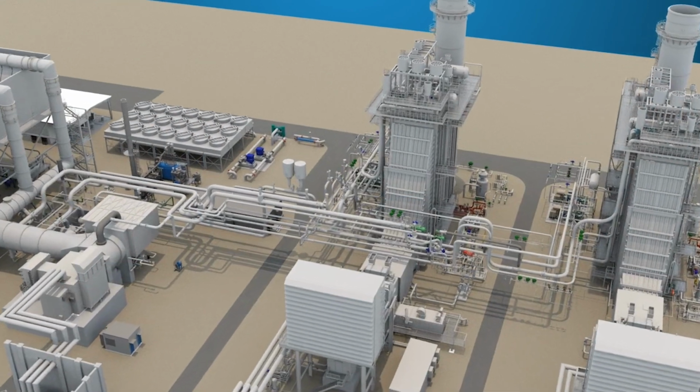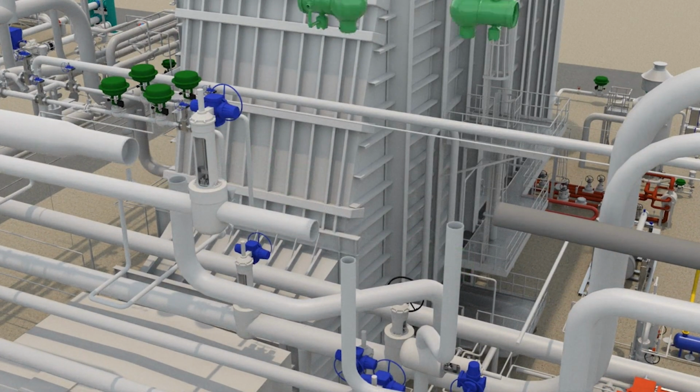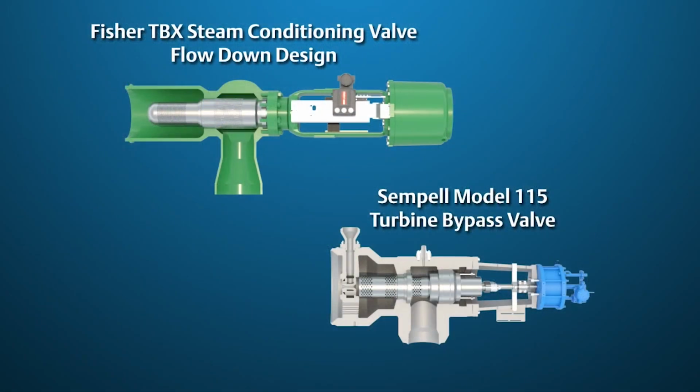In many cases, if there is sufficient headroom for the actuator, CVX valves can be converted to TBX valves for easier maintenance and better noise attenuation performance. If headroom does not allow for a standard TBX to be retrofitted, there are flow-down options that provide excellent noise attenuation by using a Sempell 115 or flow-down Fisher TBX.